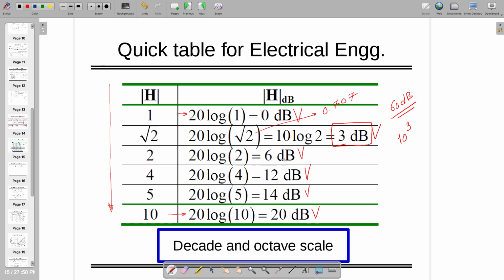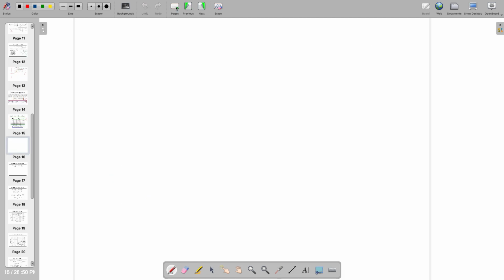If you are doubling something, I can ask you, let's say 200 volt per volt, how much in decibel? By using the following things, like 20 log 2 is equal to 6 dB, right? How much is 200 volt per volt? Is it 46 dB? 46, okay, right? So you have to look at these numbers, and those numbers have to be on your fingertip.